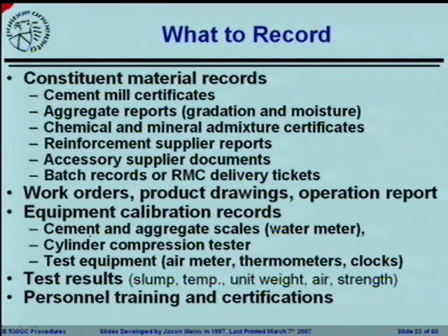A few years ago, there was a producer who was being held to a very strict strength requirement on concrete pavements, and as he started to produce his concrete, all of a sudden he started to realize that they weren't getting the strengths that they normally get. This is the same mix that they've used over and over again, and they started to try to figure out what the issue was. The aggregates seemed okay, the mixing process was the same as what they were doing before, and they were convinced that it was an issue with the cement. So they pulled some cement samples, they looked at the mill certificates. The mill certificates looked exactly like they always had. They got one about a week later, and all of a sudden all the C2S, C3S, fineness numbers were all different.